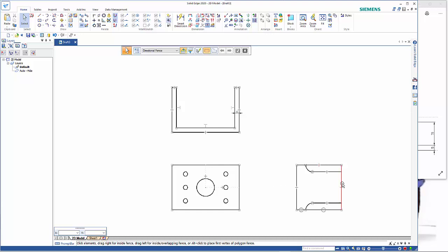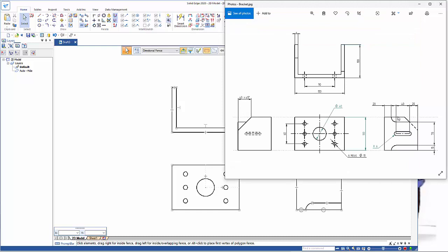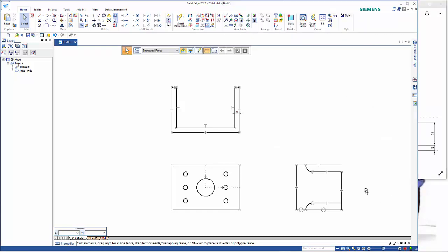We've also got a 45-degree angle on there as well, so I am going to use the trim command and get rid of that piece. So this is 40 in from the end, so it's going to be 60 long there. So I can pick up on that point and just redefine it as 60, and that will drop it back in nicely. Then if I click on the line command again, my angle wants to be -45,